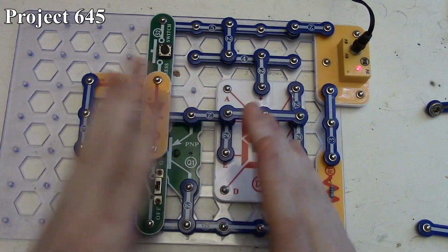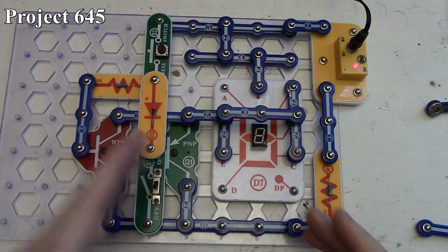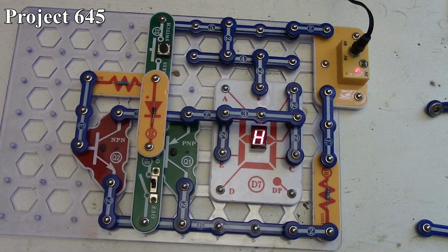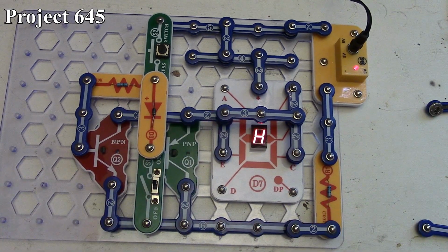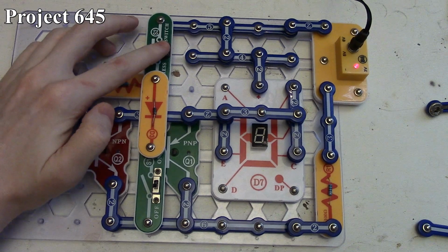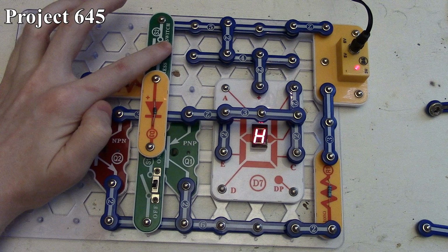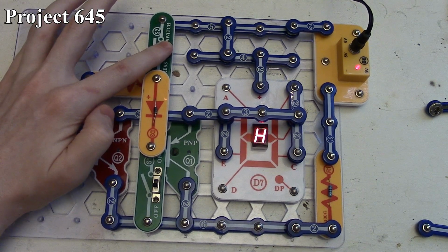So in the case of this, as you see right now, with both the press switch and the slide switch turned off or in a false condition, we have a false output on our 7-segment LED because there's no output on it. When we turn our slide switch on, we get the H there indicating a high or true condition. So our slide switch is true and our press switch is false. Now if I go up to the press switch after turning that off, so now the press switch is true and our slide switch is false, and we still have a true condition on our output there.